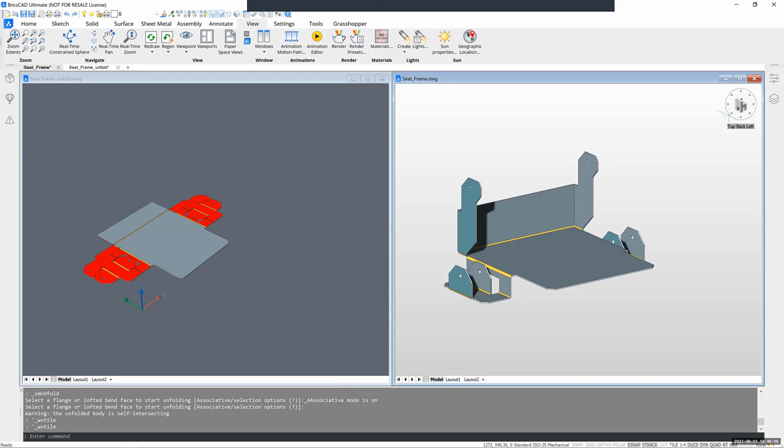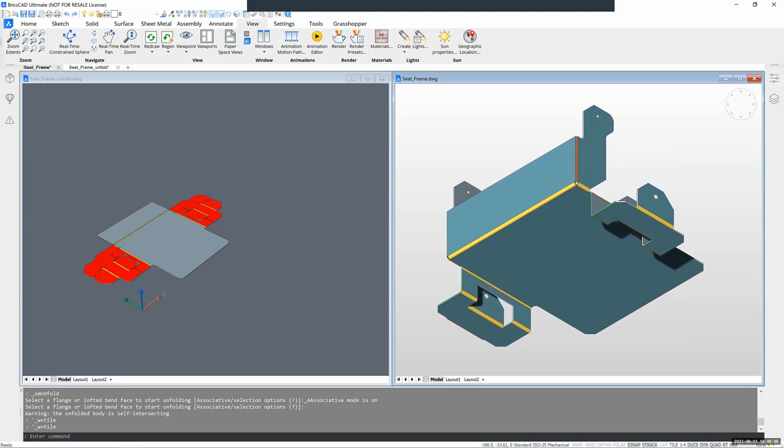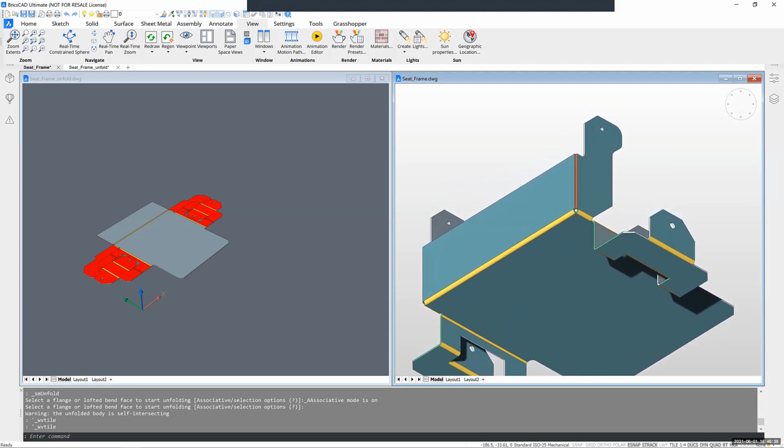Now I want to go to the bottom back left. So from the look from, to do that, I hold down Control and hover over the look from. Then I get all the down options, such as the down back left. And then you should see this part. And we will try to switch around these bends and junctions so that we can see if that would give a better unfolding.